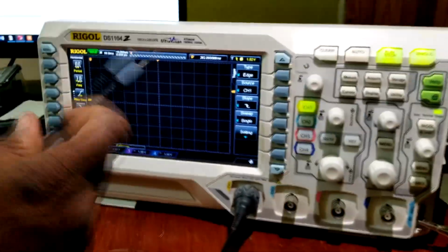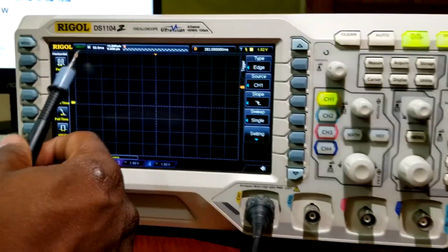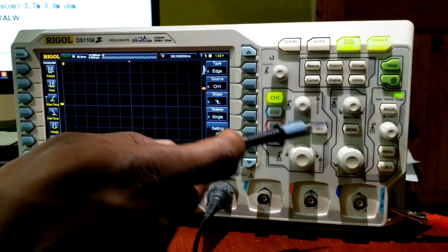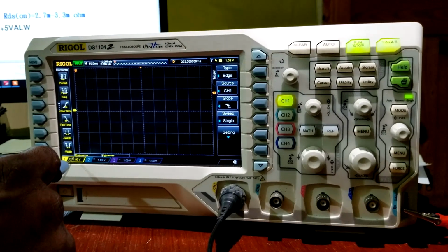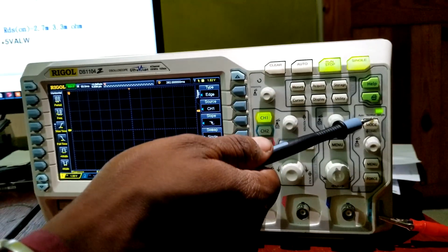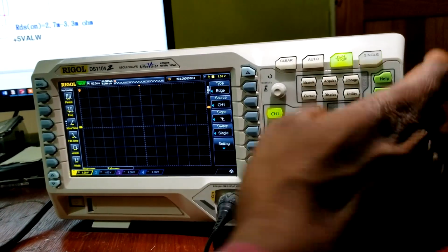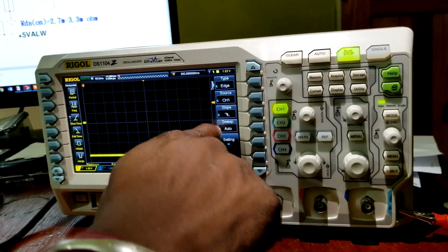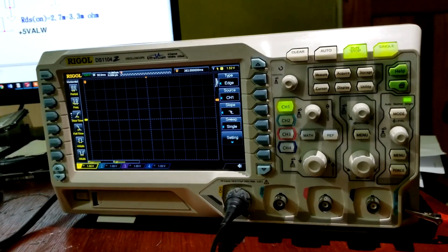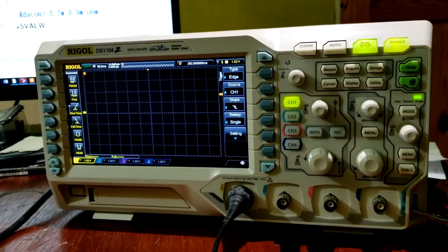Alright, so as you can see, we have the wait option here, and this indicates that we're in single trigger mode and it's waiting for a trigger and listening for a signal, right? So I have my voltage per division set to 1 volt per division. Also it's set to single trigger mode. I can hit mode and I can disable. I set it to auto sweep, single, right? And it's on waiting. So I'm going to hit the power button now.